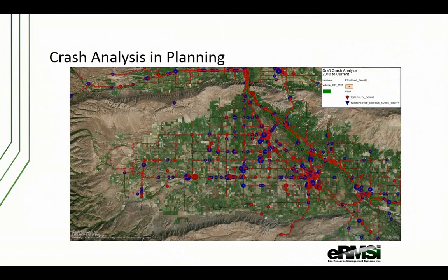One thing we have been doing on almost every model now, whether it's included in the budget or not, is actually adding in crash data. Just X and Y location, overlaying it over the model. We can do crash rates and so forth. It can help to highlight locations where we have problems.